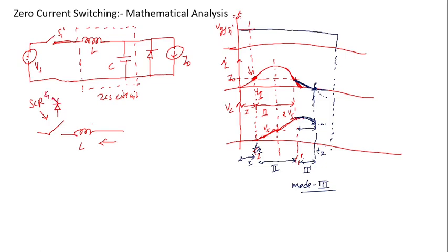and there is some gate circuit here. This is a semi-controlled switch, so it is unidirectional in nature. It cannot carry the negative current. That's why this inductor current cannot go in the negative direction. Let's say this switch is bidirectional, like a MOSFET.